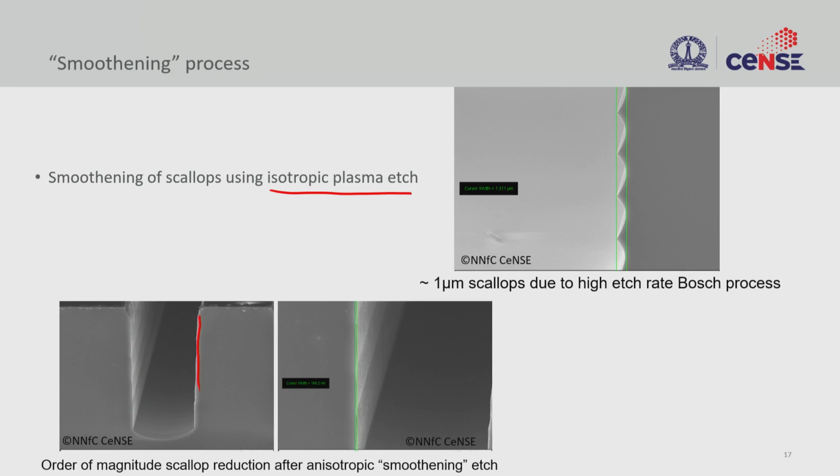It's completely gone. It's a very smooth etch process, right? So by using a combination of isotropic and anisotropic, we were able to etch very deep trenches without having this isotropic artifact.